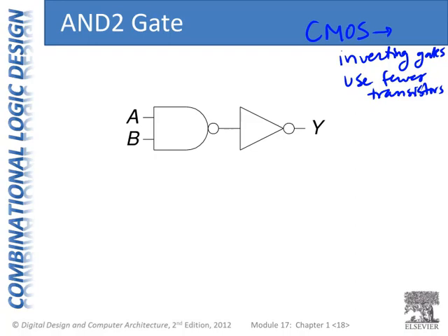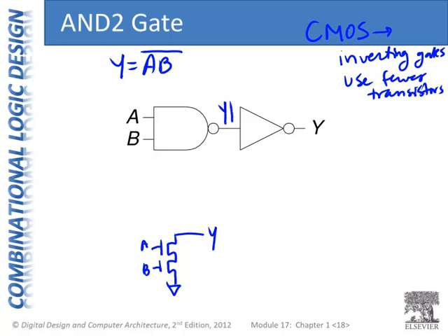So at the transistor level, a NAND gate, well, let's see, Y equals A and B, all of that bar. So we could do this, Y bar equals A and B. Here's our NAND gate. I'll call this Y1. So our NMOS is in series. So our PMOS will be in parallel. And I'm connecting it by name.